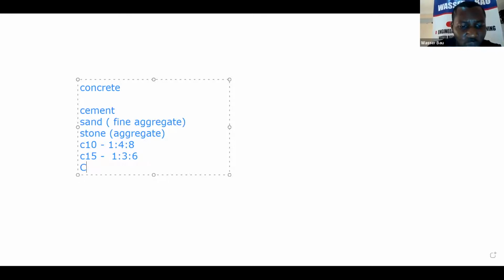If they now say it's C20, which is the most common one, this is the one you must take cognizance of because that is the basis, that is the standard. C15 is used for mass concrete, for places where we don't require heavy load, heavy point load, heavy shear load, just normal day things. C10 is for blinding, just like a waste, in quotes. In fact, these days, nobody uses it. Some people say they have stopped using it, which I agree. But knowing what cement is doing to us in Nigeria, we can't rule it out.